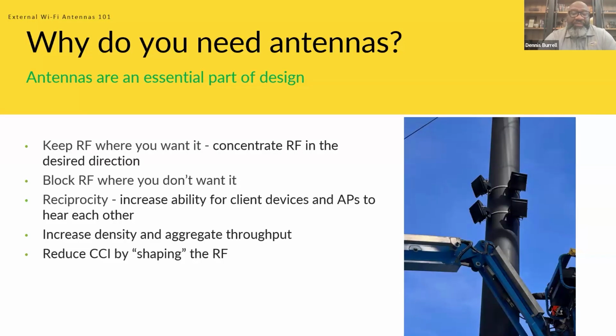Reciprocity, you can increase the ability for client devices and APs to hear each other using external antennas and higher gain antennas than you typically see on your APs with internal antennas. You can increase density and aggregate throughput, and you can also reduce co-channel interference by shaping the RF.